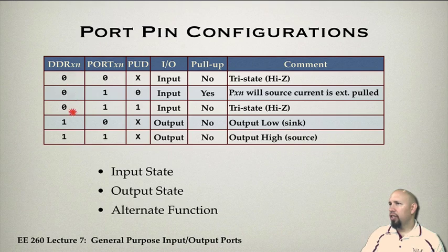So the data direction register bit for the pin associated with that port determines whether it's input or output. If it's 0, you're getting inputs. If it's 1, you're getting outputs. However, what actually is on those port values? Remember, port is where you control things. That's what controls what's going on with the pin, either writing the values or altering certain aspects of the state.